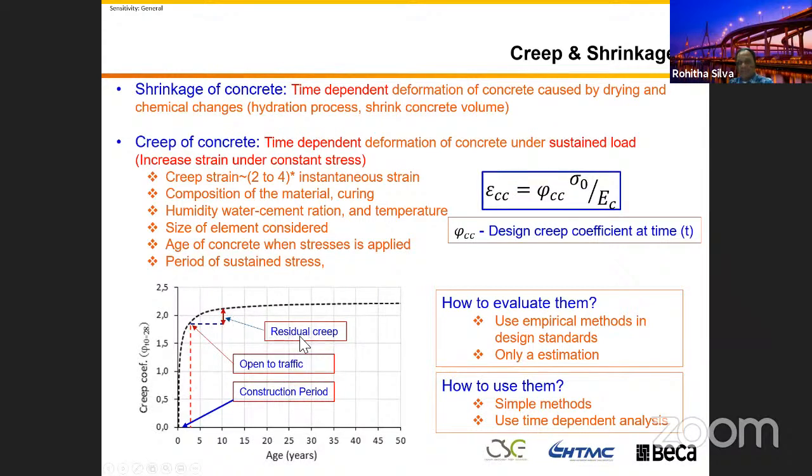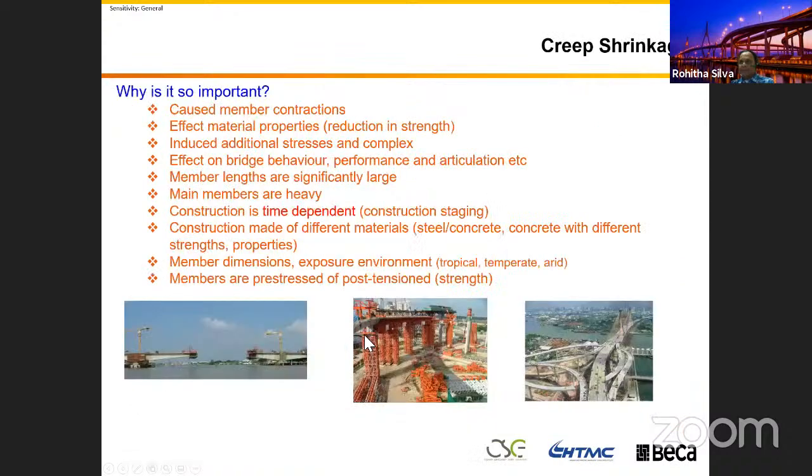I put that residual creep in this figure to show you what is left when you open the bridge to traffic. That's where the expansion joint will actually count this residual creep. So sometimes if you come across these problems, you can look at that very carefully. And the only thing, if you go in this path, you need to make sure your construction will follow the way you assume in your design.